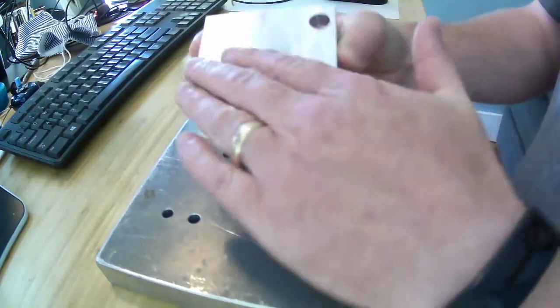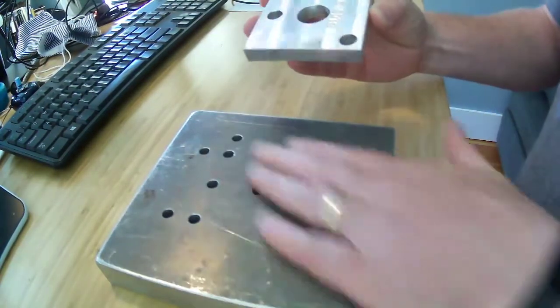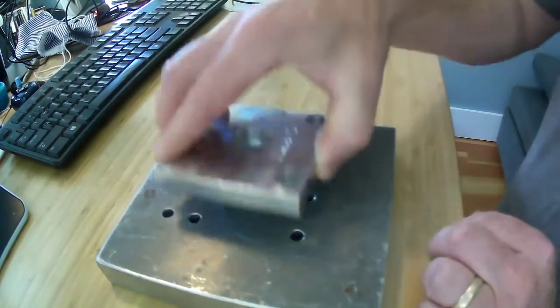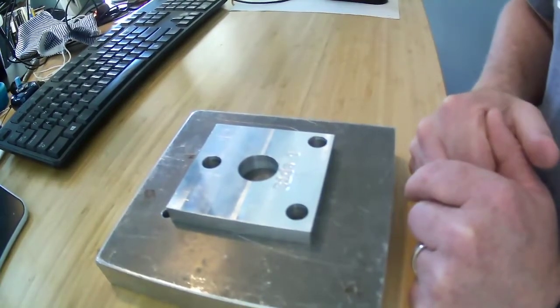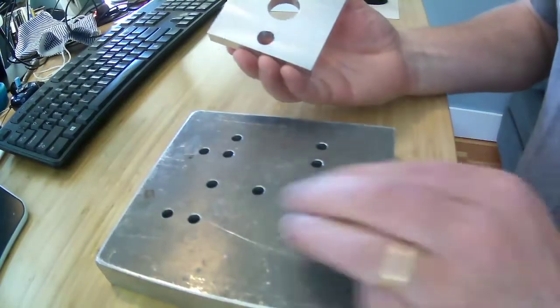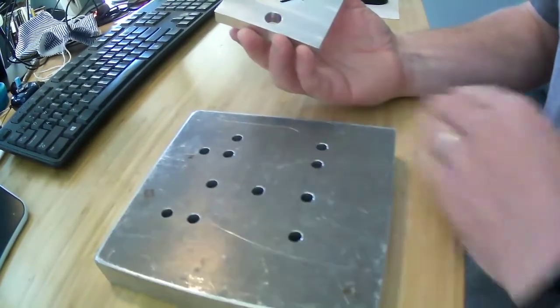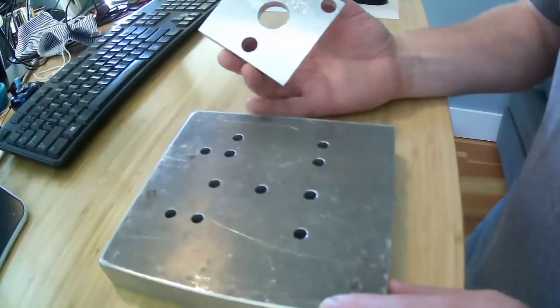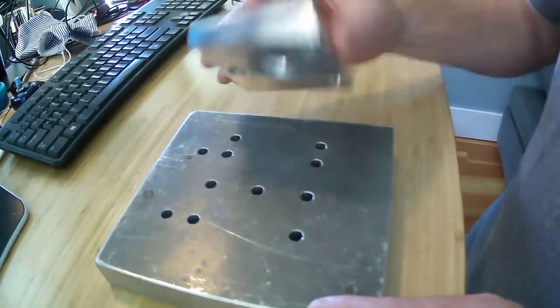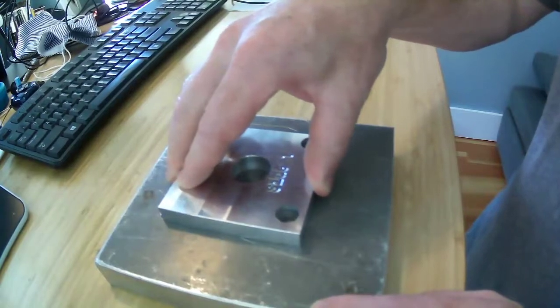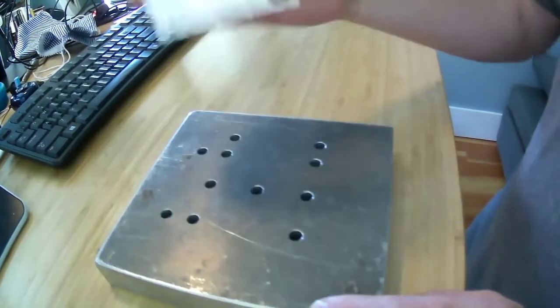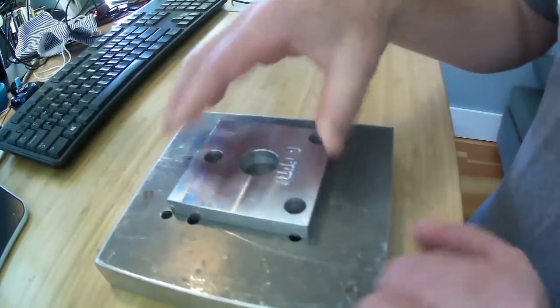I could do a microscopic mapping of this surface, and then a microscopic mapping of this surface, and I could figure that out. In machining, the way that they do that is they cover this with something called bluing, which is just sort of ink that goes on there, and then you put this part down, and you might move it around just a little bit, and then you pick it up and look for where the blue spots are, and those are the places that it's touching.